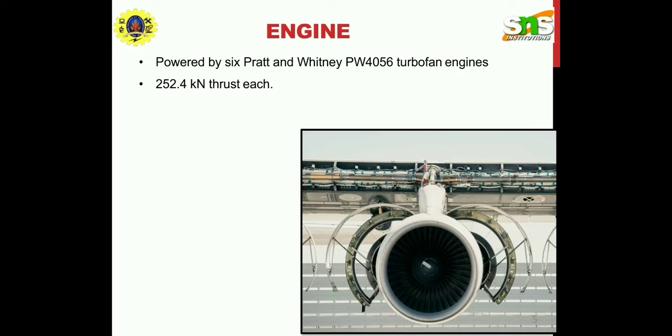In addition, turbo machines can finally be classified by the relative magnitude of the pressure changes that take place across a stage. Impulse turbo machines operate by accelerating and changing the flow direction of fluid through a stationary nozzle. The nozzle serves to change the incoming pressure into velocity. The enthalpy of the fluid decreases as the velocity increases.